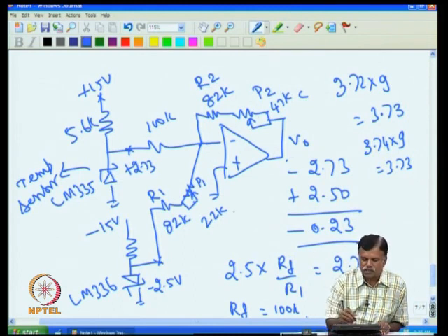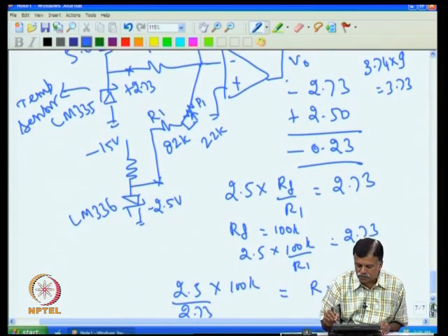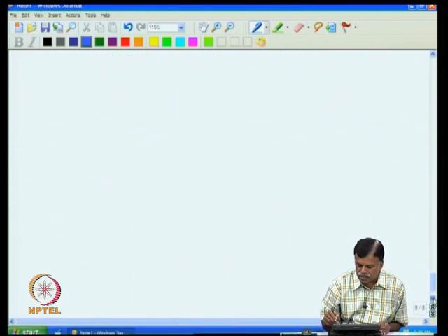That means that you have to iteratively do 3-4 times, because when you are adjusting P2, in fact this can also get altered. So it is essential that you go back and readjust at 0 degree C at P1. So you have to adjust P1 and P2 iteratively a few times to get the correct value.